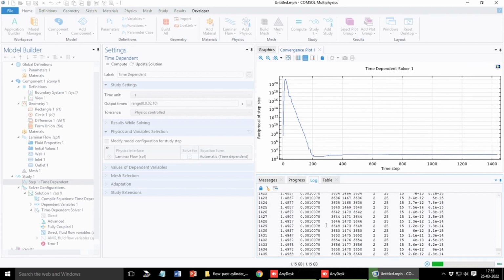A couple of more things I should highlight about the software use is that as you try to work on complicated problems involving complicated geometries and more than one physics, for example, if you have fluid flow along with heat transfer, like natural convection, you will have this problem of multiple physics getting coupled. In that case you have to choose two physics right from the beginning, or you can also add it later on.